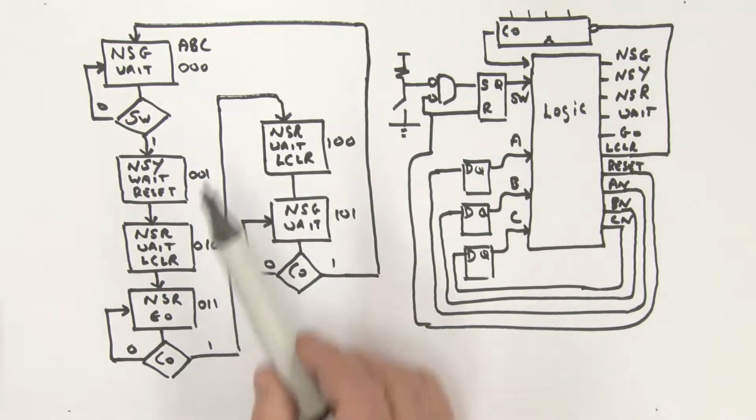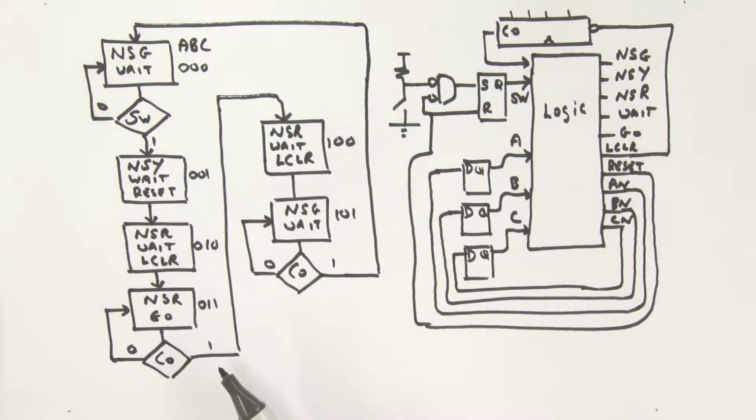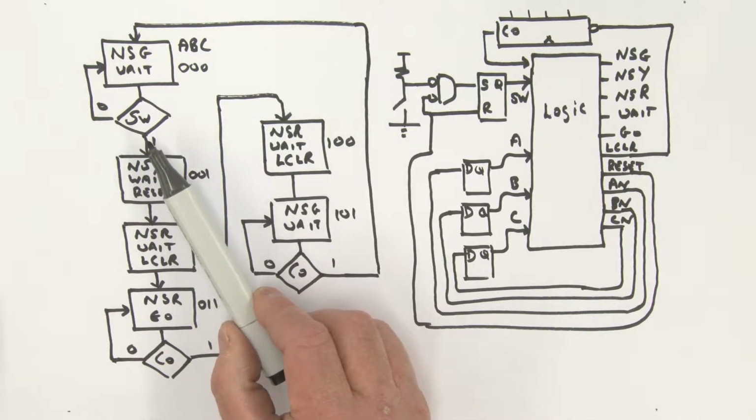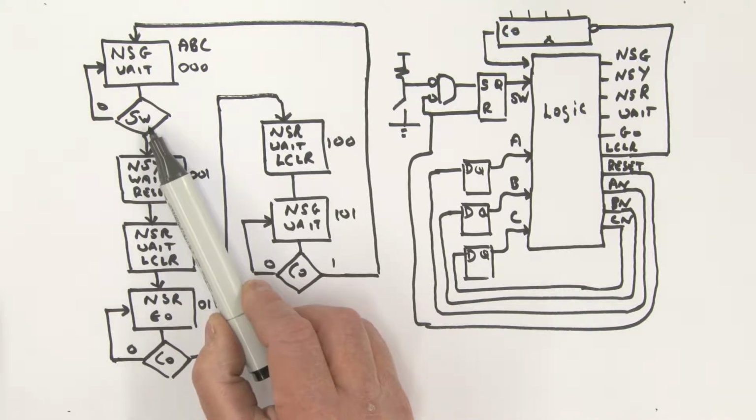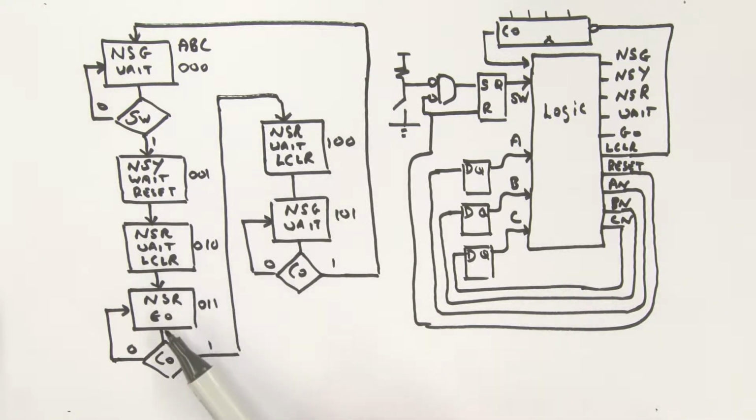Okay, in the last video, this was the state machine that we were considering. This effectively is our completed traffic light system. This now incorporates an SR latch, the output of the SR latch being this input to the state machine, SW. We also have incorporated a counter, which is providing a timeout feature for the people to actually cross the road. So when we move into this state over here, it's a 4-bit counter we're using, so we're in this particular state for 16 clock periods.